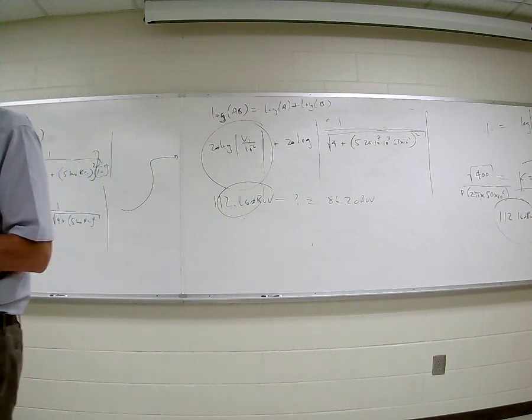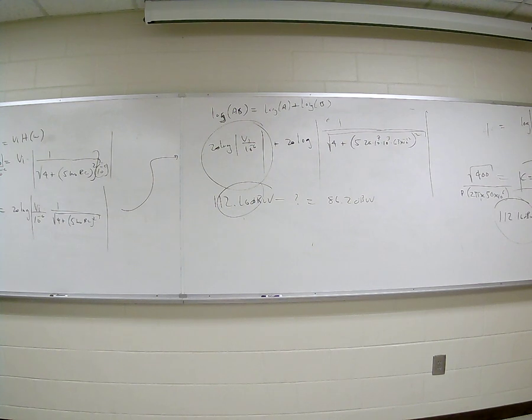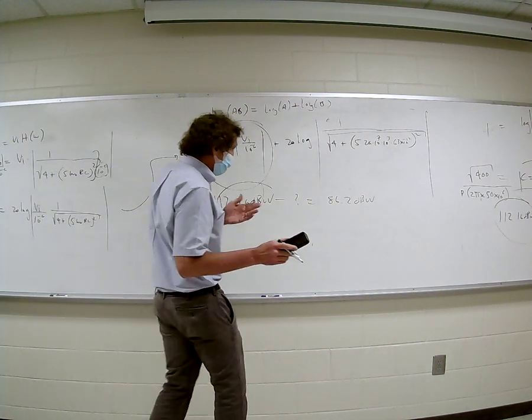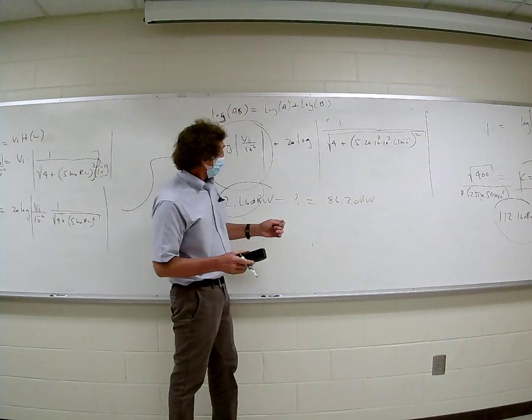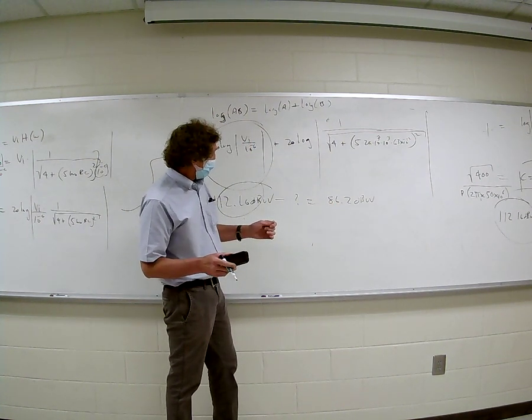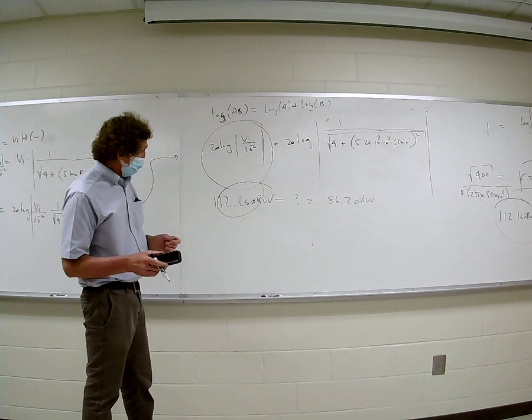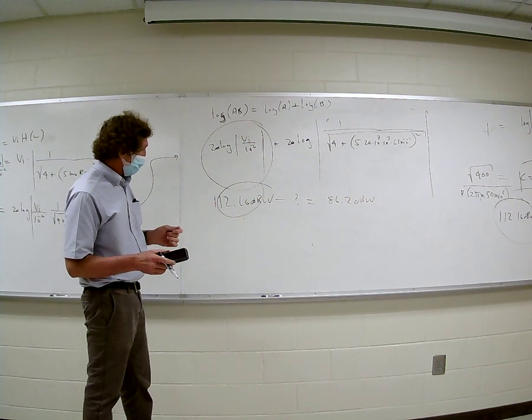All right, I want to make this point. We calculate the value of the capacitor so the input would be down by 20 dB, but the input without anything was 1/2 the actual input, right? So when we figure out the total attenuation, we're going to get at least 20 dB, more than that. I got that as well. 86.18. How many dB is that? That's 26 dB, right?